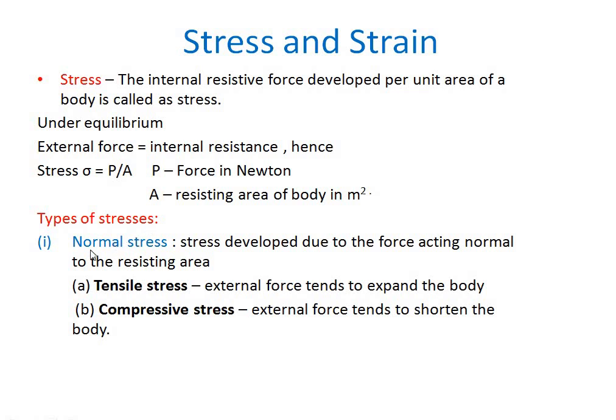Types of stresses. So depending on the mode how the force are acting, we classify it into two. One is the normal stress. So stress developed due to the force acting normal to the resisting area. So here the external force acts normal to the resisting area. We classify normal stress into two: tensile stress and compressive stress.